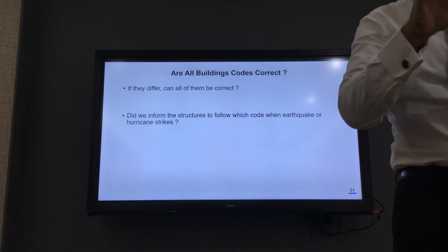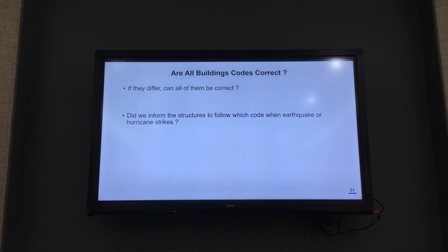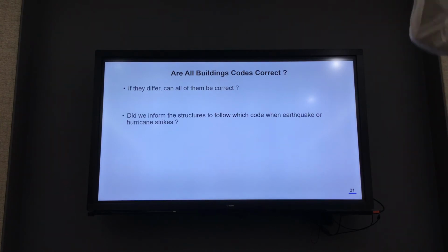So you people understand the concept a little bit, but step by step: flexural reinforcement increases the moment capacity and changes the moment curvature curve, and hence the total forces that the structure can resist will increase, and that increase in forces will make the shear fail first, because for moment you have already provided enough capacity, right? Because of that, when people come with 4% reinforcement in the shear wall, we say don't do that, make it 1%.